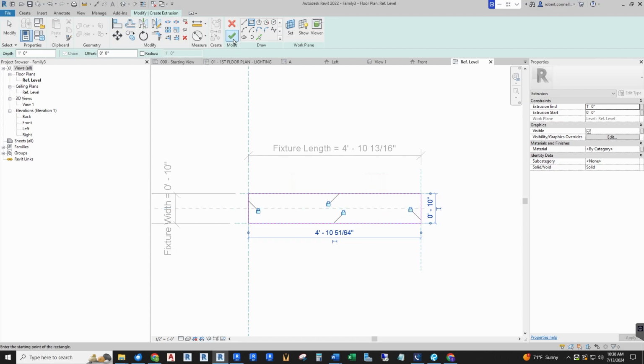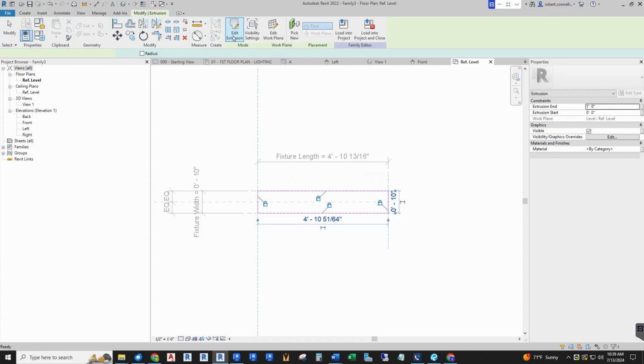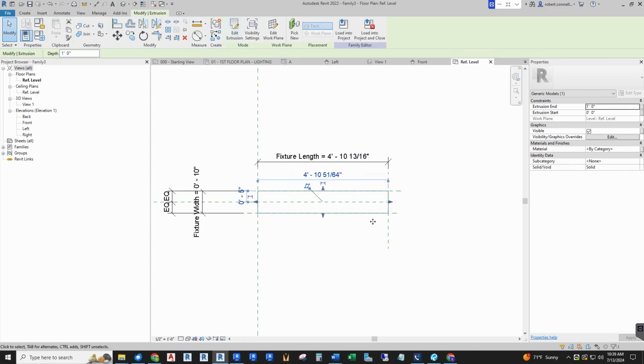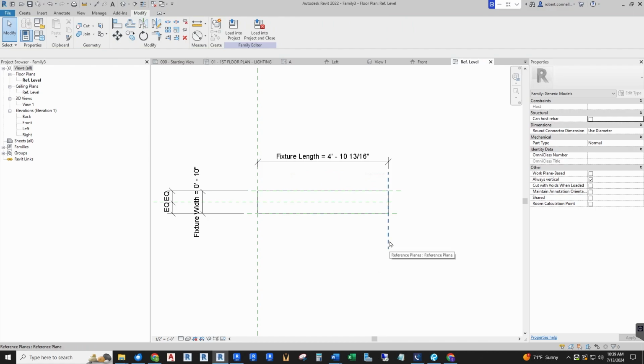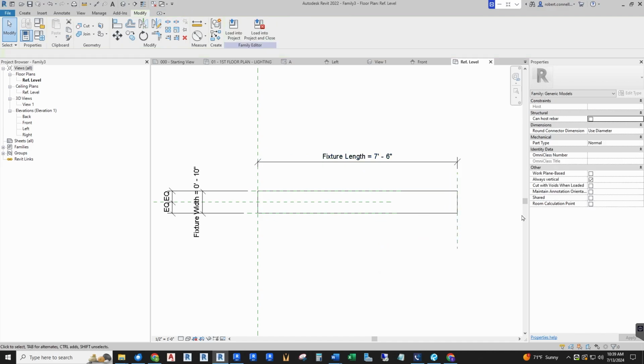Now we get out of here and just call your attention to an extrusion is a 3D box, and so the depth which goes into or out of the screen is set here as 1 foot by default, which is fine because we can change this when we get to a cross-section view. So click OK on this. Now we have an extrusion and it is pinned, locked to these dimensions. Let's test it. Move this dimension and our extrusion goes with it.